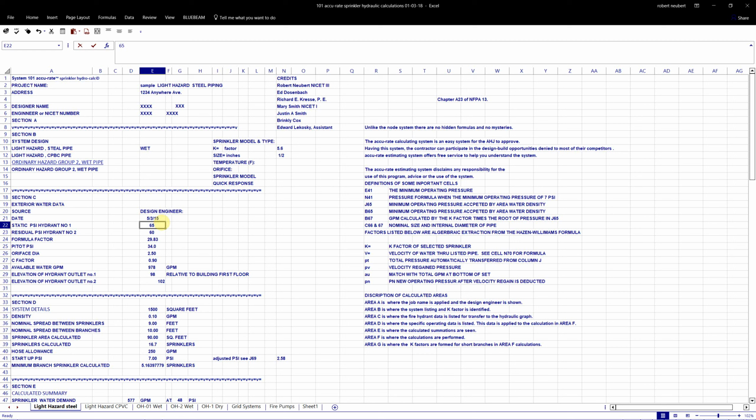Open the flow hydrant to the last turn to maximize the full flow. Read the pitot pressure and note it on cell A23 of the calculation page. Someone should be reading the residual pressure gauge and then give you the sign to stop the water flow. Close the hydrants slowly to avoid damage to the main or hydrant. These are very important instructions. Once this data is entered, the program will calculate the GPM flow in cell E28.